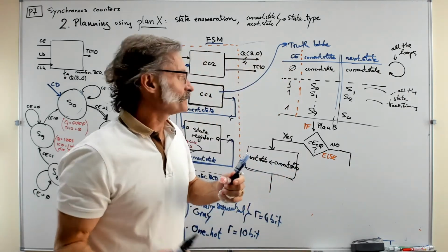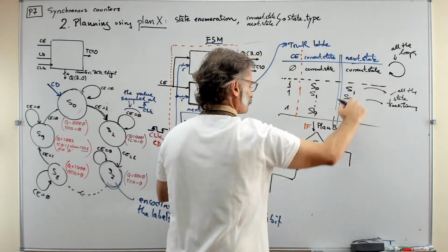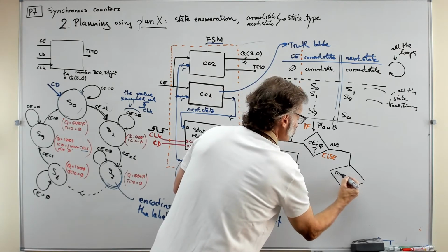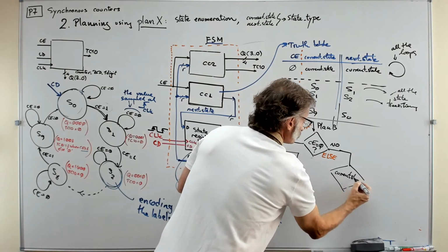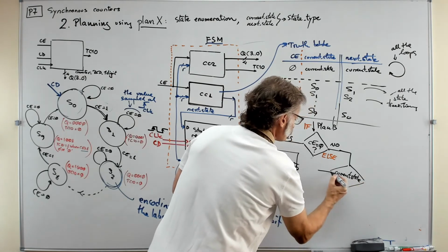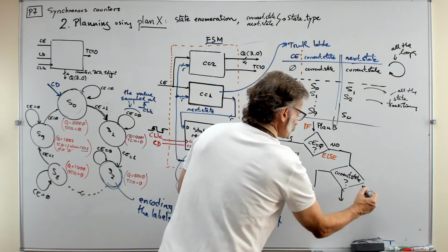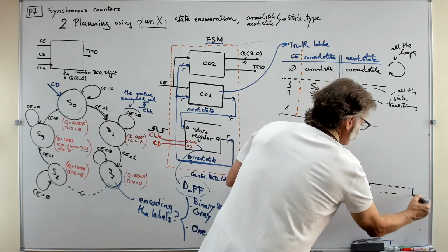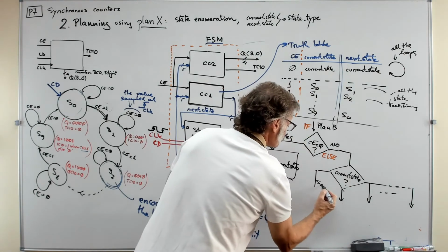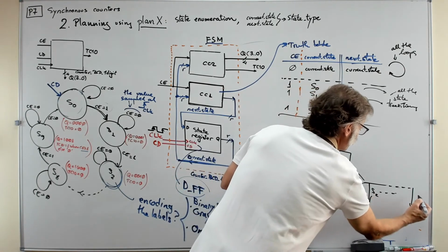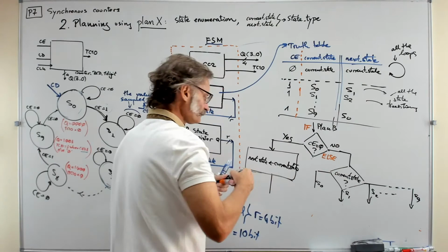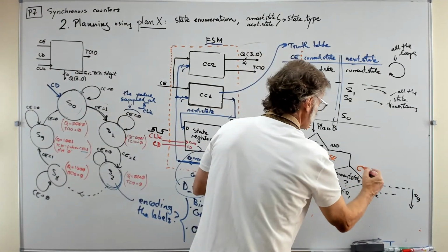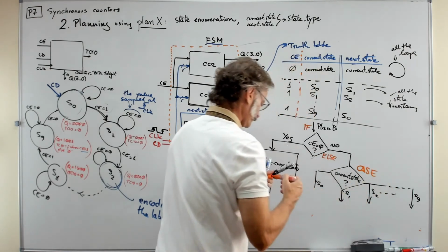What is going to happen in this else? Well, now is when you are going to solve this subsection of the table using the case statement. So now is when you ask for the current state, for example. What kind of current state you have? Which is the level of this current state that you have? S0, S1, S2, S9. So depending on the current state, this is what is translated as a case structure.